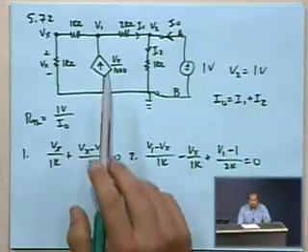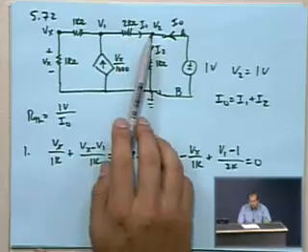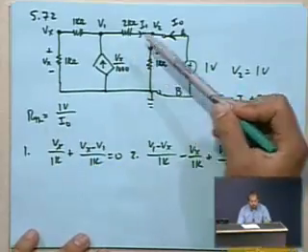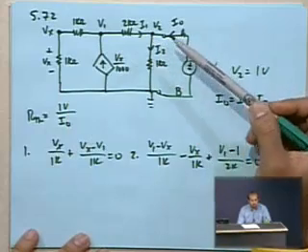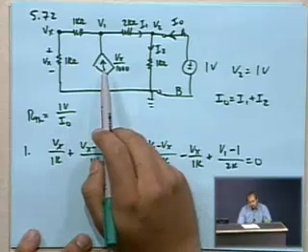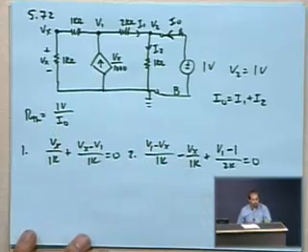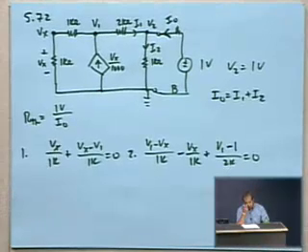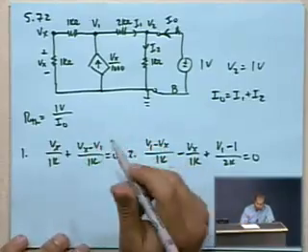So once we find out what the node voltages are at V1 and V2, then we can find out what the current I1 is, we'll find out what the current I2 is, and that'll tell us what I0 is. You could solve perhaps more directly for it if you were going to use mesh analysis instead. But again, because of that shared current source, that might not be a very fun way to do it, in my opinion. So let's try to solve this.